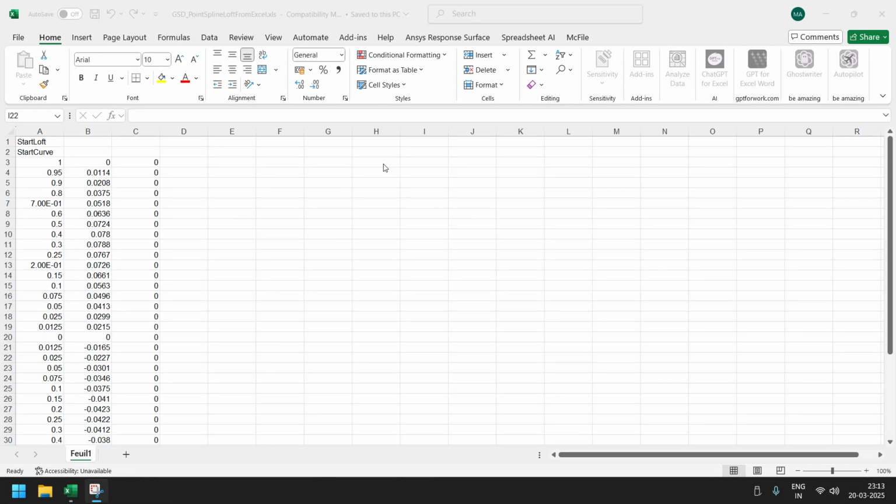So I'm going to explain 3D flow simulation over a semispan wing. I'm going to use the NACA 2412 file. These are all the coordinate points x, y, z. That is three coordinates we have to import. As it is 2D, the third column is 0.